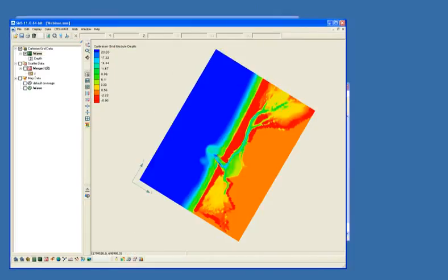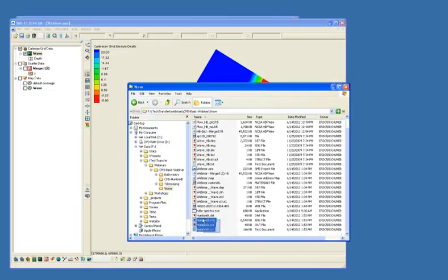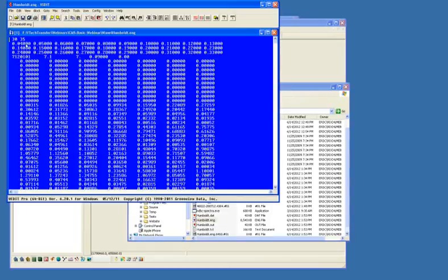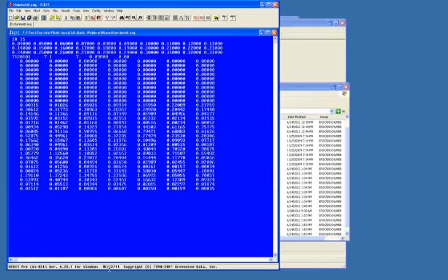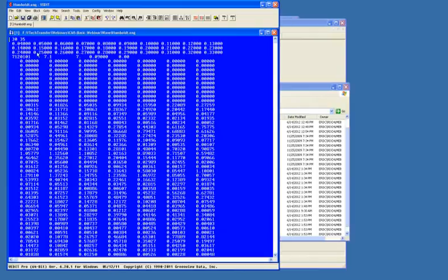And so it's finished now, and it's written some files out in your directory. The one we're mainly interested in is the one with the .eng ending. And the format looks like this, which is exactly like the format that ST-Wave uses for its half-plane model. And you notice that the index here at the beginning of this line is representative of the year and the date. So this is 2007, December 1st at 1 o'clock in the morning.